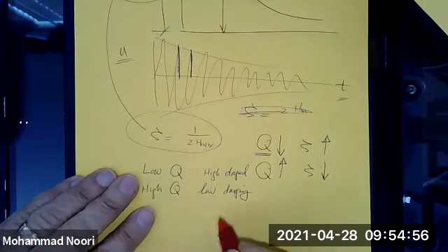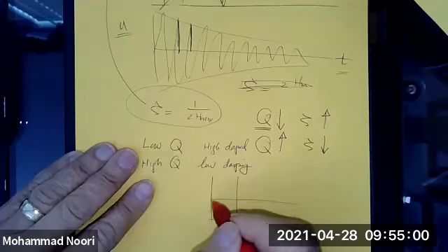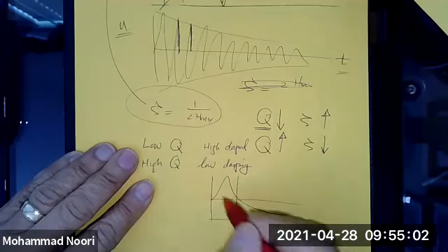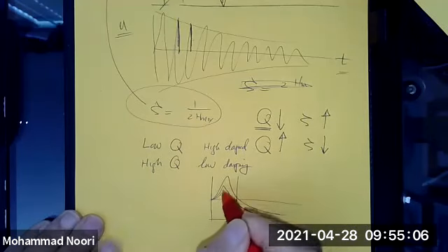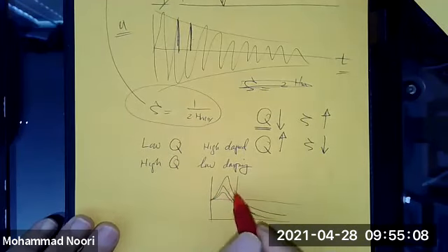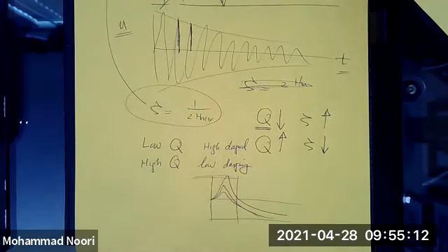Okay, and you can see it is obvious, right? Because if you plot it, the higher the value of the damping is, the more this peak is going to drop. So that means you have a lower maximum value, which corresponds to the determination of the damping ratio in the system.